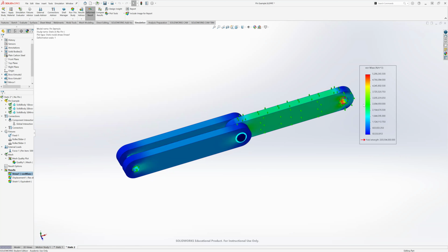And even with something like this, you could figure out the cross-sectional area of a thing here and figure out I have this much force going here. Again, it's not the most accurate thing because obviously the force is applied here, but you could say the force is applied evenly along this entire face. So it's really easy to do a quick stress calculation. In this case, there'd be a normal stress, sigma equals F over A, and see, are we in the ballpark? There might be slight discrepancies, but if you're like 3 times off of what simulation is giving you, then you either want to check your calculations again, or go back and see maybe what I'm doing in simulation is not accurate.